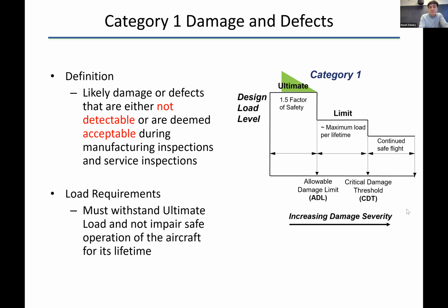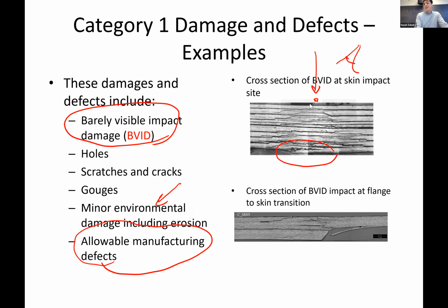Okay, so this is acceptable damage, acceptable defect in the material. So next time you're in a composite aircraft, know that there's probably cases like this, that there has been damage, lots of micro cracks in the material. The backside is cracked completely, but the structure is designed to have these types of defects and still carry 1.5 times maximum load. So these are all fine damages.